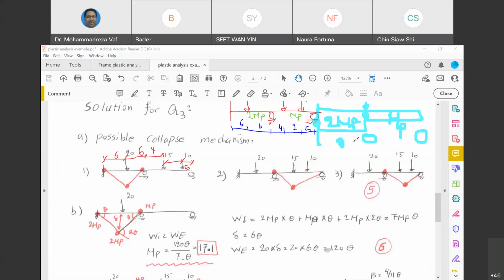So this needs to be understood very well when you're calculating the internal work. Right now in this beam, you can see that when I have drawn the condition for collapse, I have written here 2 MP, because 2 MP is given for the cross-section size of the left span. And then under the beam also is 2 MP. The bending moment can reach 2 MP.